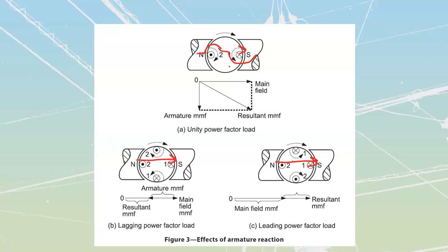If I go to a lagging power factor, the lagging power factor is going to set up another fake pole. So this over here is going to give me a bit of a fake pole, and this over here is going to give me a bit of a fake pole as well. What I want you to look at now is that these here are rotating around. They're pushing out like this, which means that as I fire lines of flux in from my north over here, it's going to be harder for me to stuff them through, and some of them are actually going to get grabbed and carried around the outside. This one here, grabbed, carried around the outside like that. Actually, I wanted to draw those two in blue so it's easier to see them. Grabbed, carried around the outside, and then in. This one here, carried around the outside, and then in.